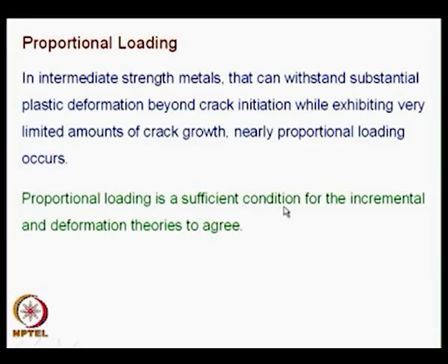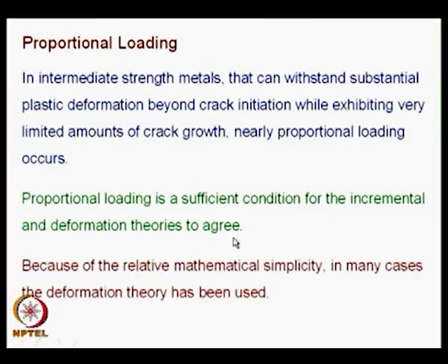Proportional loading is a sufficient condition for the incremental and deformation theories of plasticity to agree. Because of the relative mathematical simplicity, in many cases the deformation theory has been used. What we want is to have the mathematics as simple as possible, yet comprehensive to capture the phenomena. So, we have to necessarily make an approximation. In certain materials you will see more plastic deformation and very little crack growth, and then this is applicable.